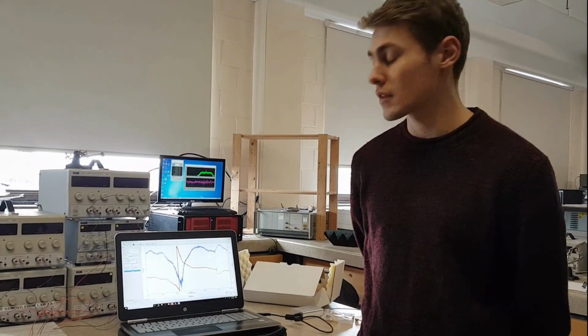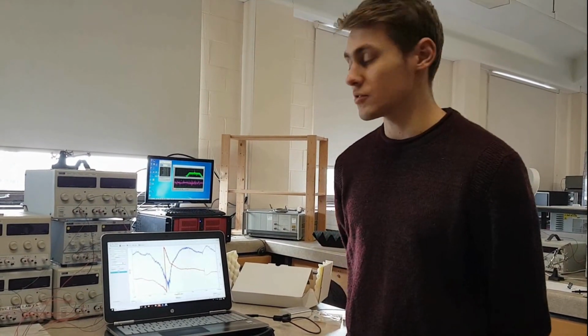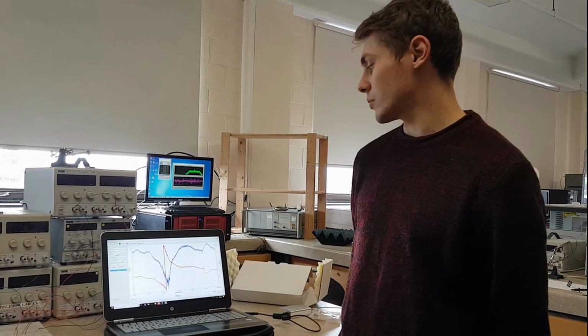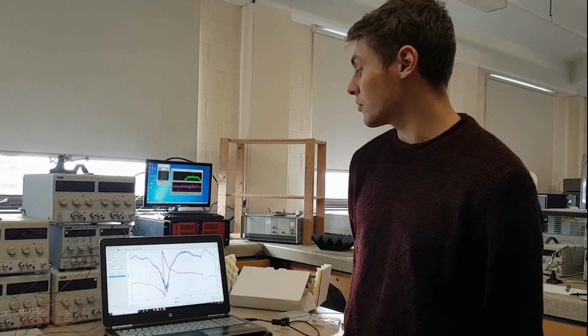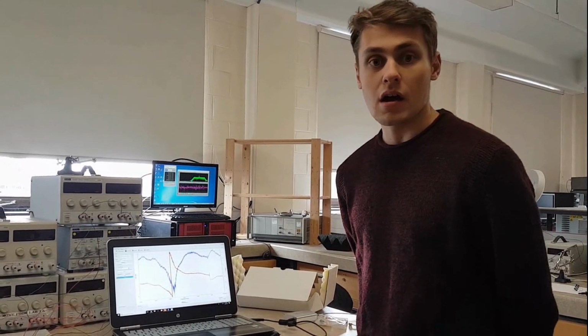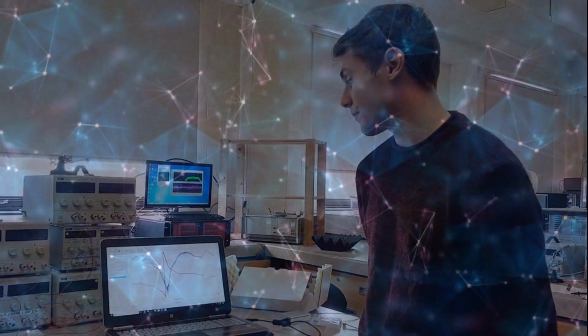We've calibrated the VNA, connected the antenna to it and run an analysis for the S11 parameter. We can see that the frequency has shifted downwards slightly, so it's now matched to a frequency of approximately 2.43 gigahertz. What we can also see is that we have good transmission at this frequency, as the power reflected back from the port is minimal. We have a power level of minus 20 dB at the frequency.